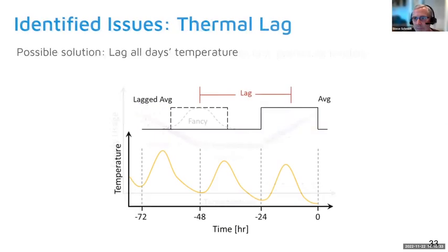Yeah, I've written about this in CalTRACK before, but what we found, at least for homes, was that using a rolling average worked great. More and more buildings are doing pre-cooling and preheating, so it's not just a thermal lag. There's also the opposite, where the energy use precedes the temperature change. We decided on a 5-day rolling average for both the HDDs and the energy use, and that seems to work really well. All right, I think that's a pretty good idea, and we'll add that to the list. Thanks, Steve.